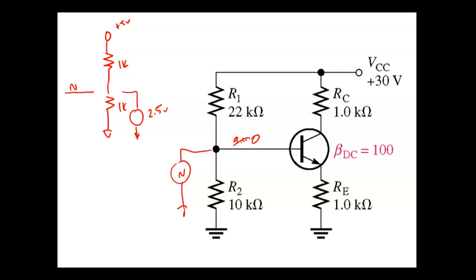So I cannot bring an AC signal directly into the base. I need something that will let the AC signal come in and block DC. So what device have we talked about all semester that passes AC and blocks DC? A capacitor. I have to use the right size, guys. I can bring an AC signal in through this. It's going to be polarized, so we have to put the plus on that side. Now I can bring an AC signal in.